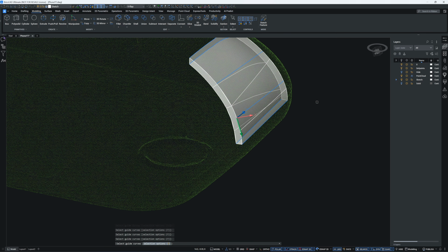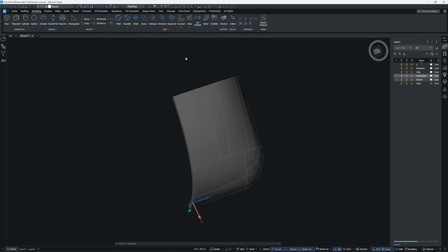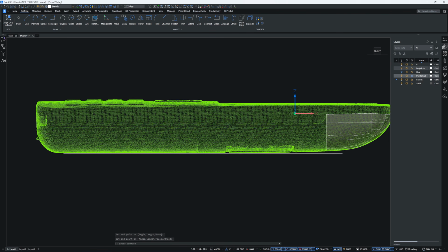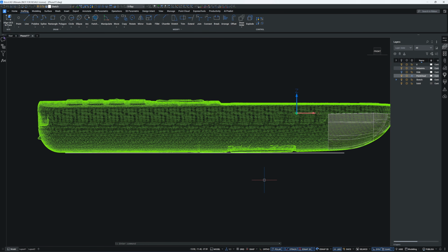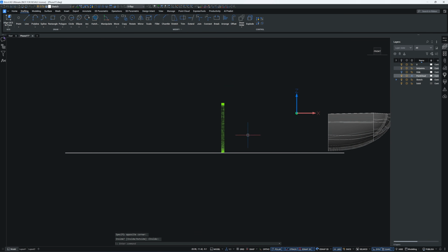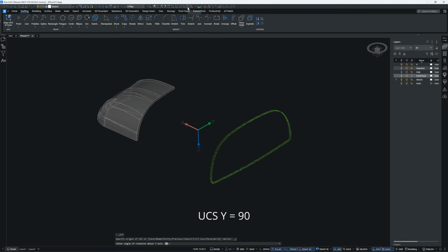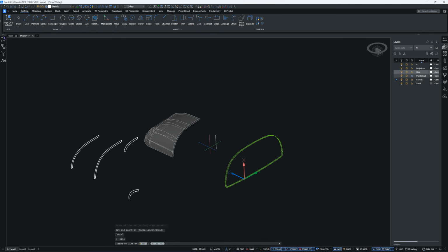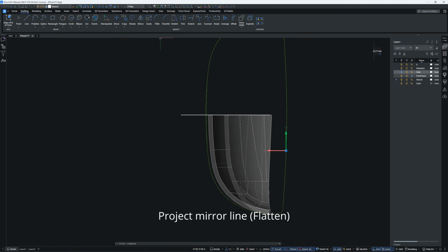And here's how you can create a dual curved shell using only the loft command. I have drawn a horizontal line here. You can see the slight taper on the right side, and I place the next cross section where the taper ends. This section has only a slight change in shape, so it can be modeled as a longer segment.